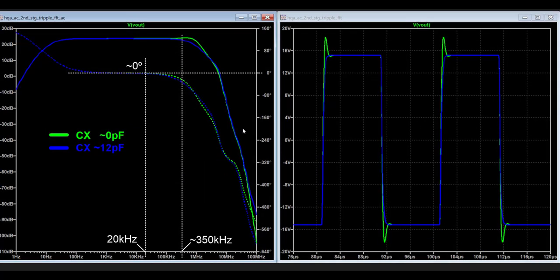these are results for closed loop. We can see that the amplifier goes from 20 Hz to 20 kilohertz. This is a plateau. The phase will be minimal between input and output. So here the capacitor will not have, let's say, a big impact.